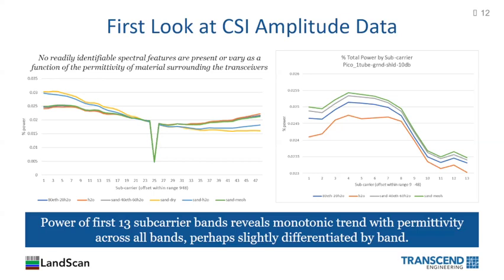And if you just look at this across the whole 64 bands, you can't see any discernible patterns with respect to the medium that it was in. But if you zoom in on different regions, you can pick up this frequency-dependent fading as a function of dielectric, which is exactly what those chips are designed to compensate for with that information, is frequency-dependent fading. And so we actually ended up working with 48 bands. I'm going to move on with that.